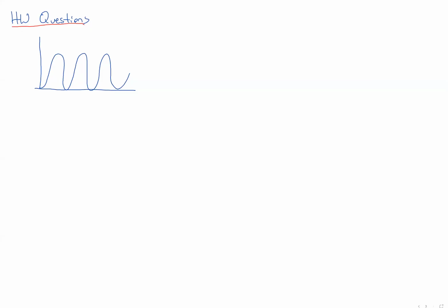So you're given a waveform that looks like this. And the question is, this is a voltage. The question is, find the RMS. So my very first suggestion, before you do anything else, is to give a rough guess. You're going to find that your intuition is really good. It's usually within about 20 or 30%. It helps to know if you're doing the problem right.